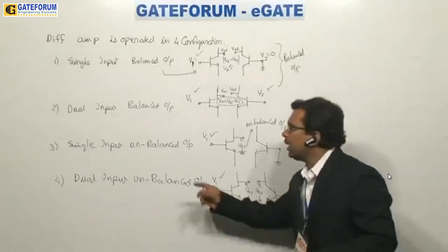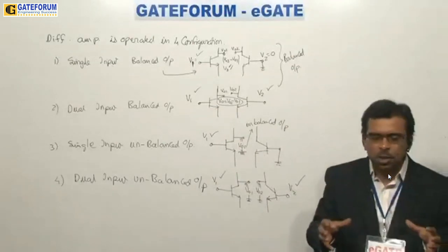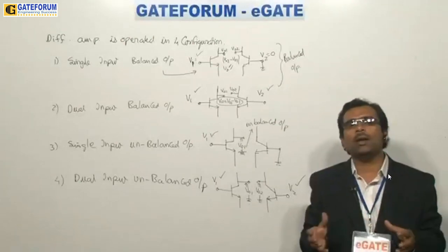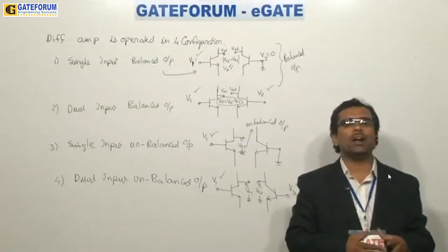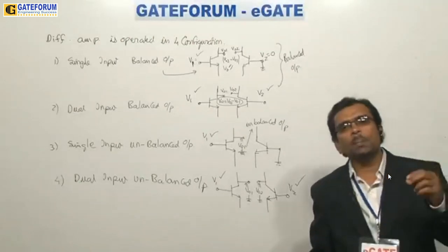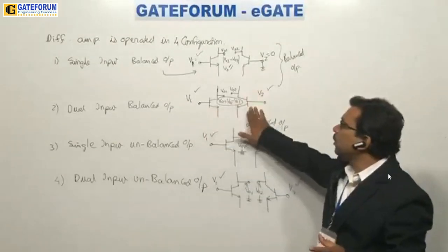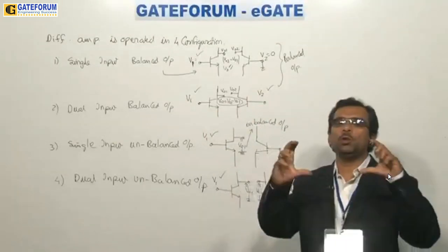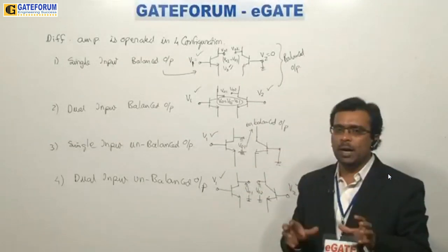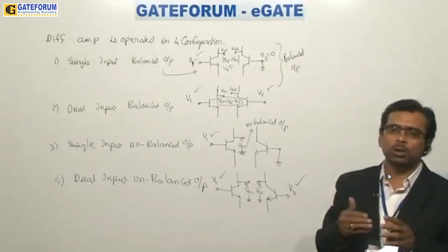Okay, because both the emitters are coupled here, and you have RE resistance and all this, what happens is that when you try to couple them like that, the H parameter analysis cannot be done in the normal way how we have taken it. Okay, it has to be replaced by T network, and the combination of these two emitters must be coupled. That becomes a complex analysis, and you'll be getting 3 loops. Out of the 3 loops, you have to write mesh equations and solve all those things.